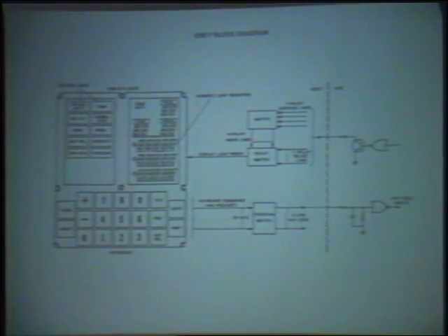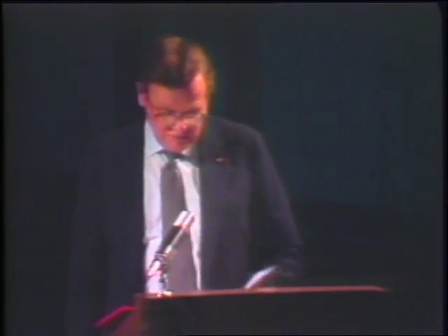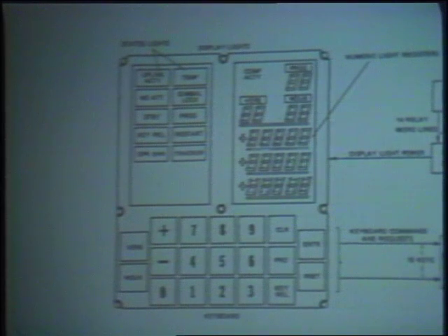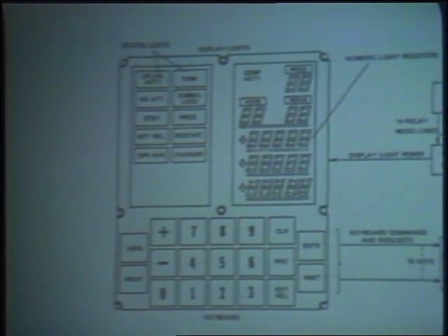Each register contains 5 decimal digits consisting of segmented electroluminescent lights. 5 decimal digits are used so that a computer word of 15 bits can be displayed in either decimal or octal number systems. In addition, there are 3 2-digit numeric displays, 1, 2, 3, that indicate the major program in progress, the verb code and the noun code.